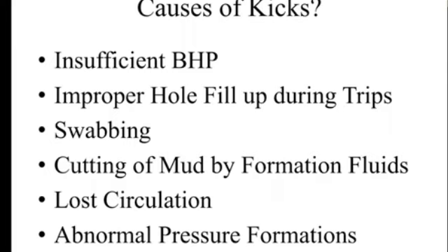What are the causes? There are several reasons, but all of them will be under one umbrella: insufficient bottom pressure. Whenever the bottom pressure goes below formation pressure, kick happens. And as I mentioned previously, bottom pressure is not a constant value.